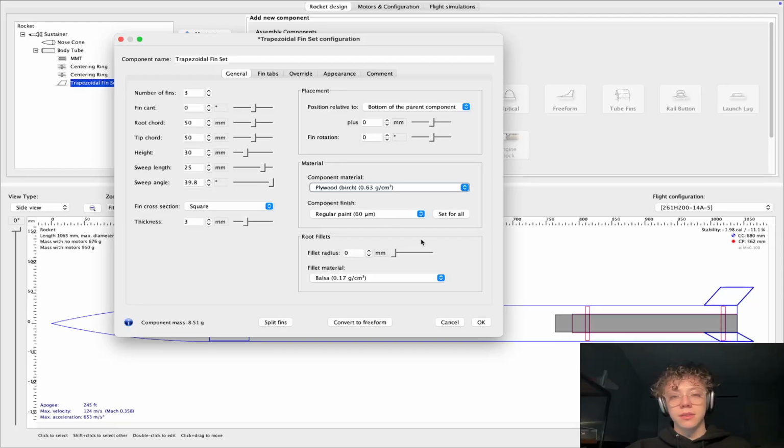So I'll go like that. And then for thickness, these will also be normally, they could be a quarter inch. I'm going to go over to millimeters, but 3 millimeters not bad, because they could be less than a quarter inch, they could be an eighth, and then you'll do a tip to tip on them, which we'll talk about. So honestly, I'm just going to keep it at 3 millimeters for now, accounting for a 1/8 fin with some tip to tip on top of it.